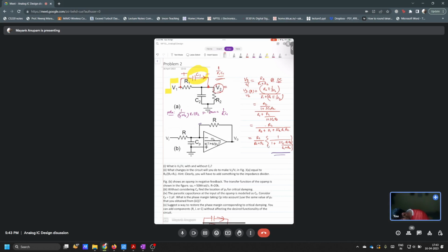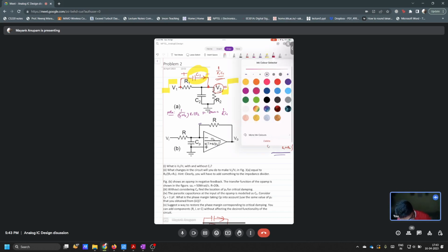But now what do you want to have? If there was no frequency dependence in the circuit, then in response to this instantaneous voltage here, the voltage V out, V2, should also be instantaneous, right? Yes, sir. But now it is lagging slightly. Now it is going slightly like this. So you make sure that there is something in the system which is going to do that instantaneous business here, right? And that is done by a zero, correct? Yes, sir.